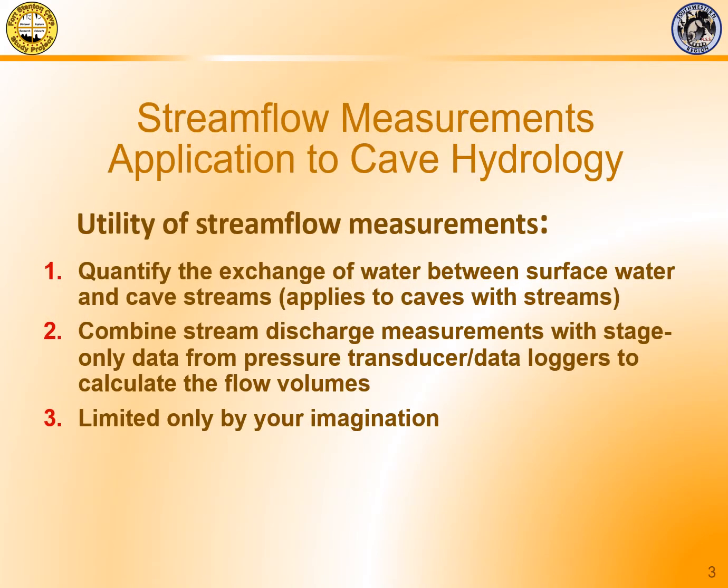What is the utility of streamflow measurements? Well, in general, we can use these measurements to quantify the exchange of water between surface water and cave streams, which of course only applies to caves with streams, such as Fort Stanton Cave. And then we can combine stream discharge measurements with stage-only data from pressure transducer data loggers to calculate flow volumes.